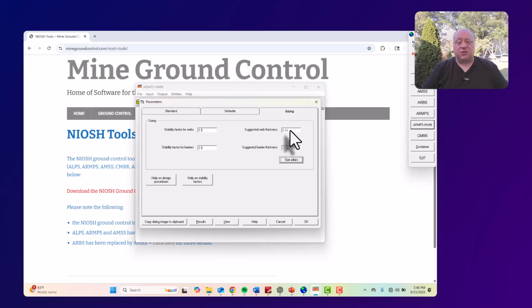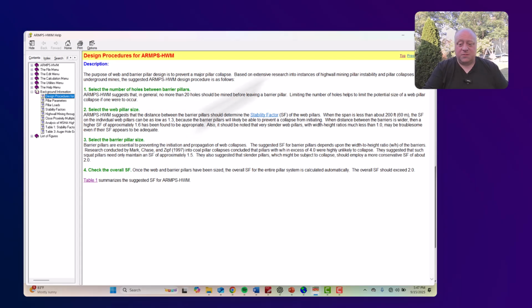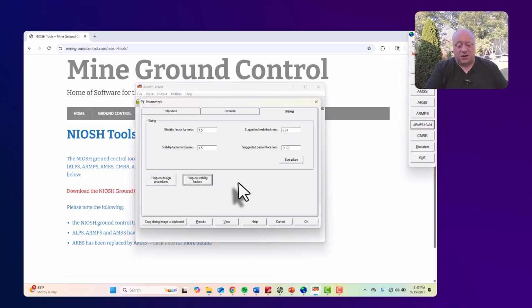We'll go into a lot more detail later, particularly once we get into the rock mechanics class, about the background of how all this works, how the stresses are calculated and all that sort of thing. But with that, this is what you need to design high wall miner holes for your basic layout. Okay, this does not include the impacts of multiple seam mining, which is more common now than ever.